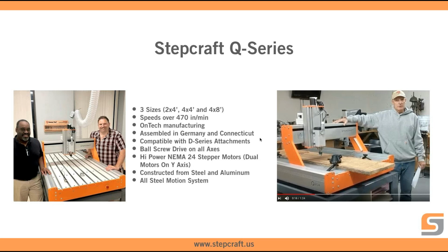So the roller, if you take the ball screws off of our gantry and you slide it by hand, I guarantee it's going to be one of the smoothest gantry operations you'll ever feel. The design, it's not cheap. There's a lot of bearings that go into each axis to get everything to move smoothly, but the design is there to ensure that there's as little drag as possible, and the machine is highly accurate.